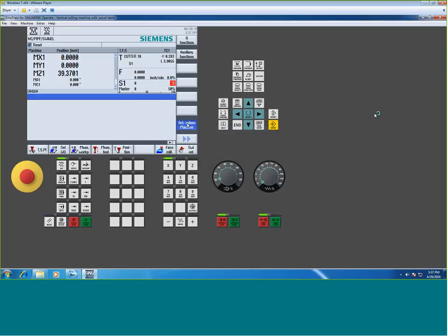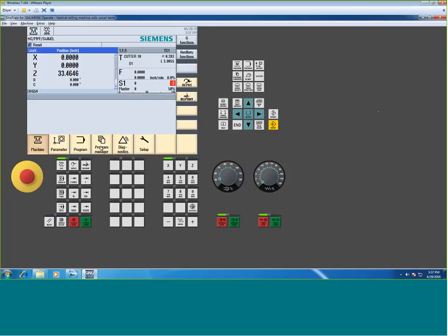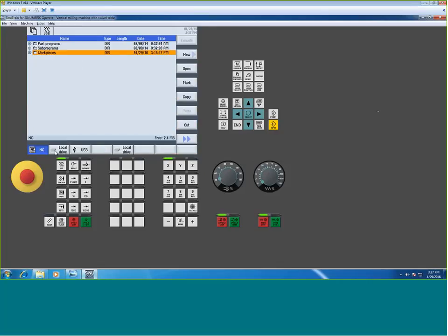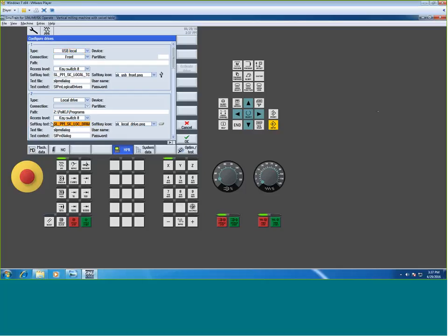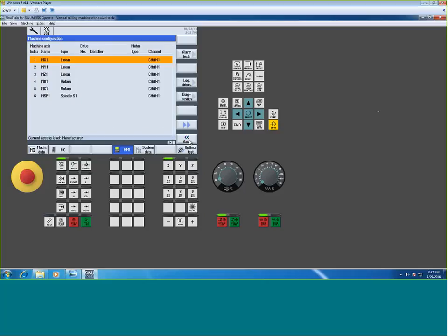Good. So we had created one and left the name the default. So now I actually have 2 local drives, and that can be a little confusing. If I want to change these names, just head on over to Setup HMI, go to your logical drives function, and it's this soft key text. You want to delete the whole string. So delete everything listed here, and now I can say I'm going to call it my program button. So change the name right here in soft key text, say OK.